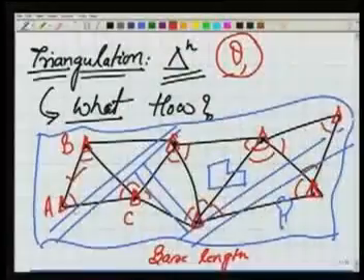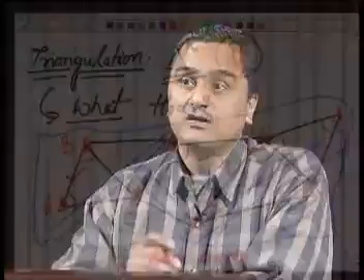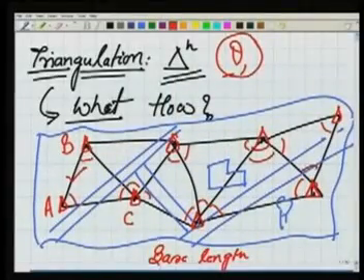You have to stretch your tape or chain along this line AC. Well, it may be undulating terrain. The length measurement is subjected to more errors than the errors in the angular measurement. So we are in a situation where we can carry out the angular measurements in a better way, more accurately, without much problems, but not the length measurements.